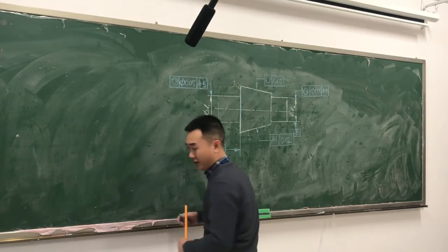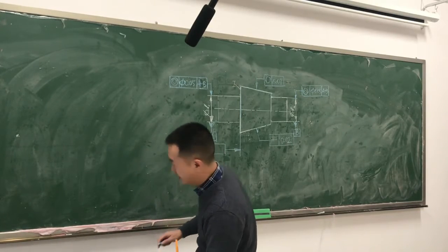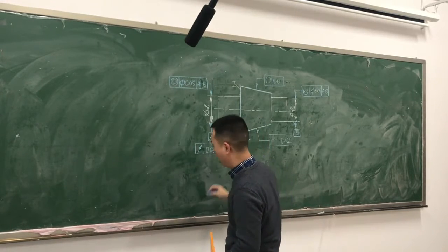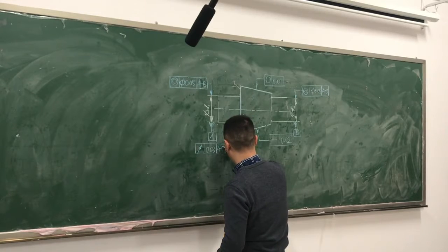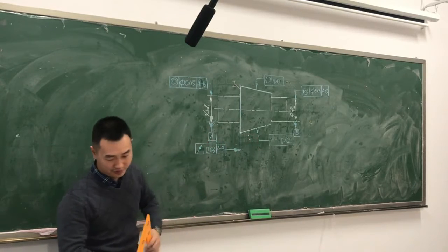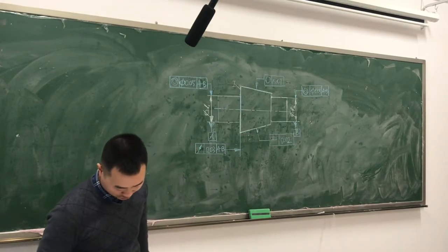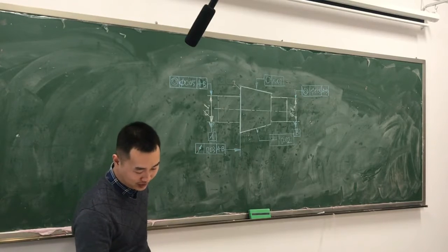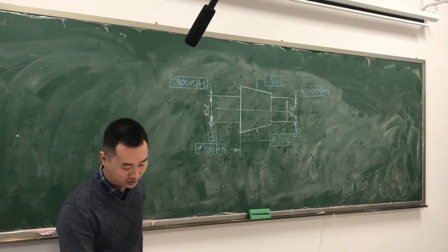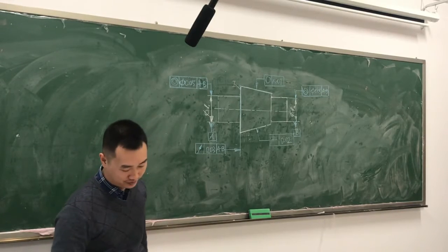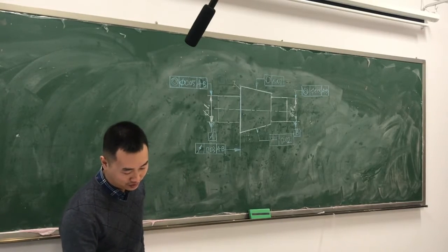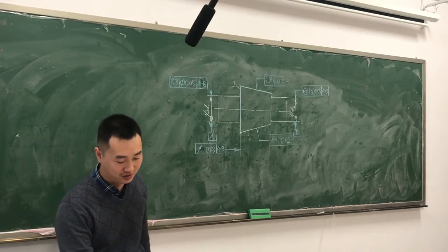So here, then we should put the tolerance value here. It's 0.03, and it has the common datum A and B. Here, because as you can see, on page 105, for circular run-out in axial direction, the tolerance zone is the place between two circles in axial directions.